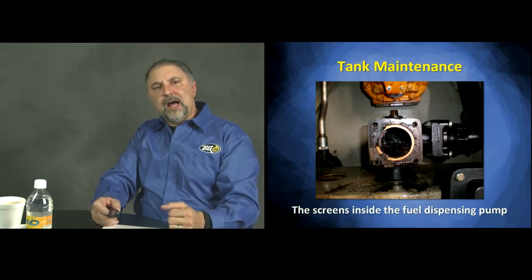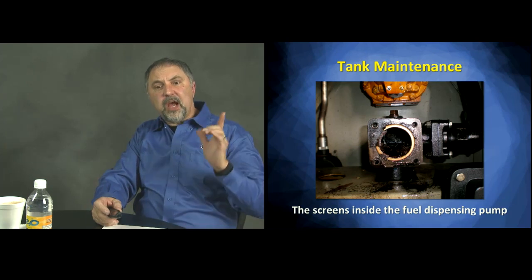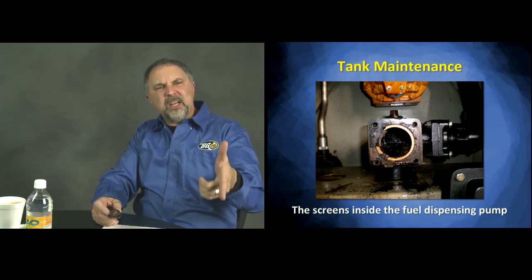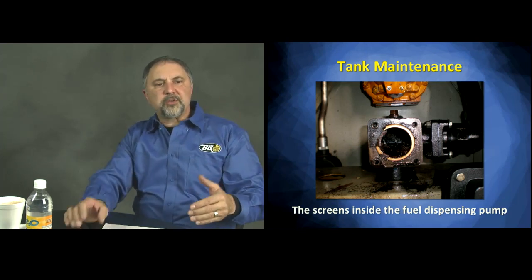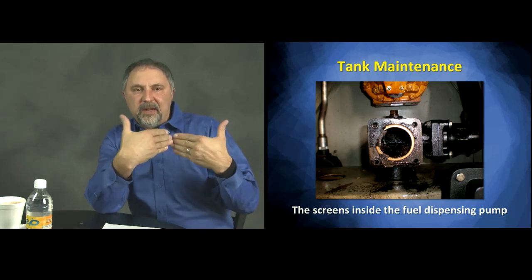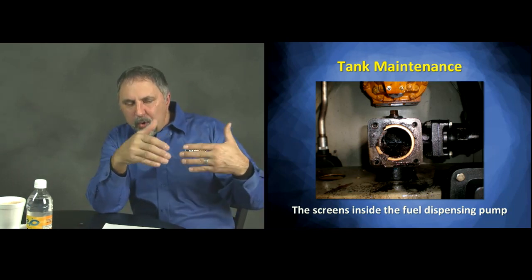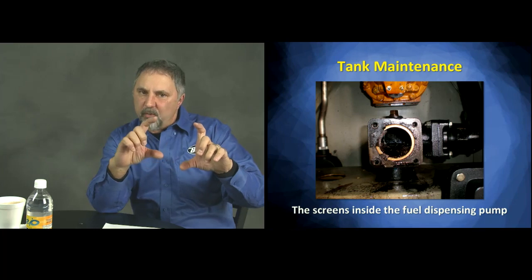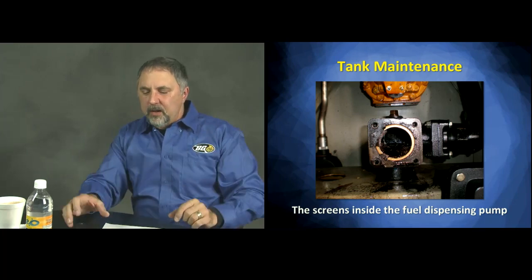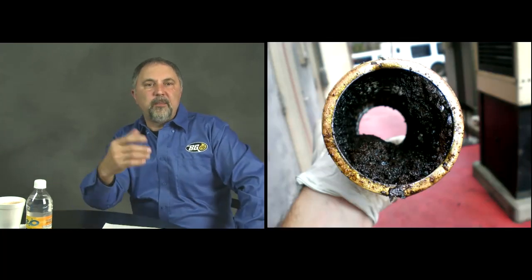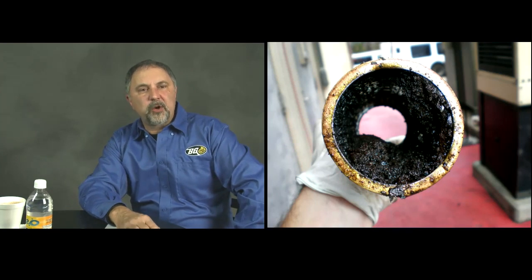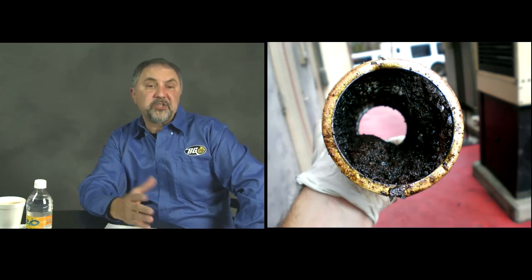On this particular slide, if you went to the gas station, you've got the nozzle and the fuel tank, and as you're filling the vehicle up with fuel, you'll see that the plate in front of it has a little key. You pull the panel off and you'll see there are 4 square holes. Unbolt them, you can pull a strainer out and you've got a bunch of coffee grounds floating in there from the underground storage tanks. That's another source.